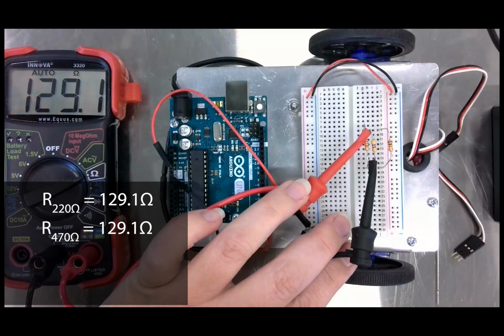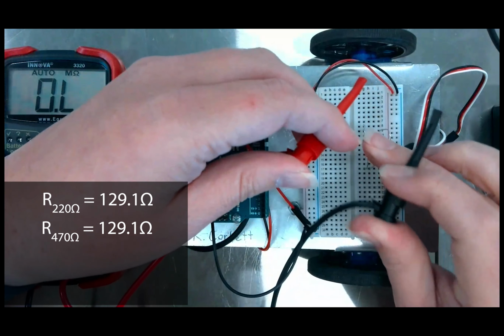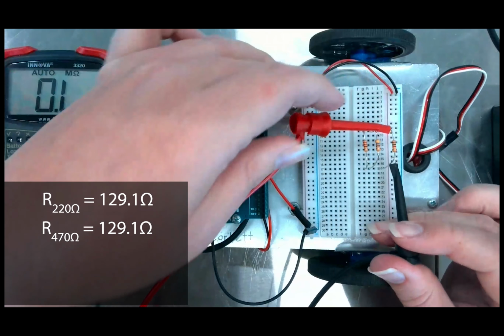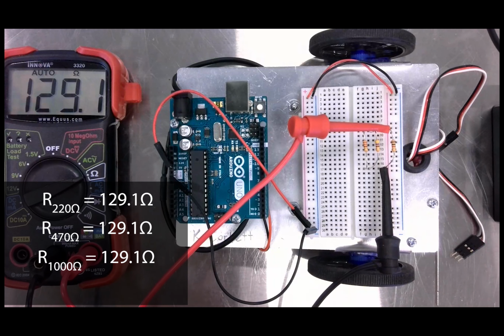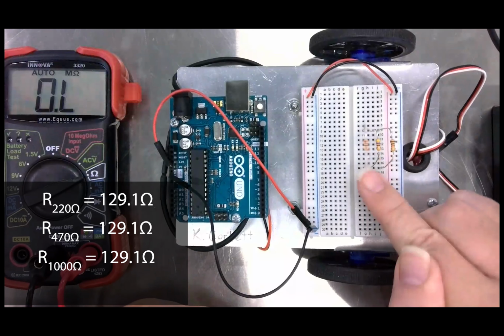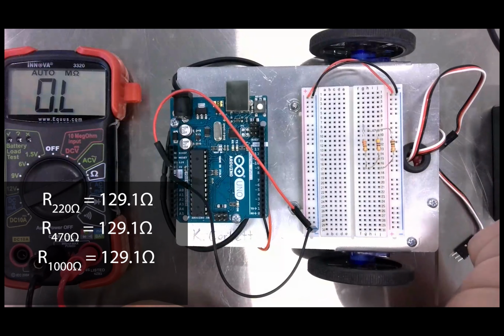Again, I get 129.1 ohms. Now let's measure across the 1000 ohm resistor. I'm getting 129.1 ohms. Why do you think I can't get the individual resistance values when I measure across the resistance?